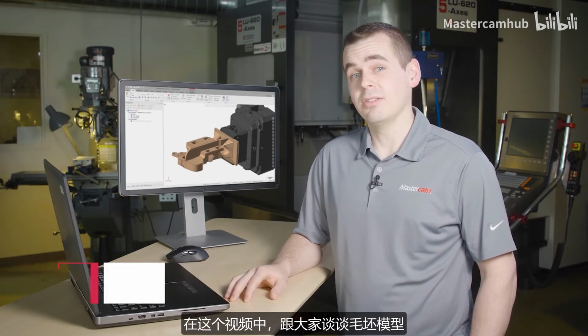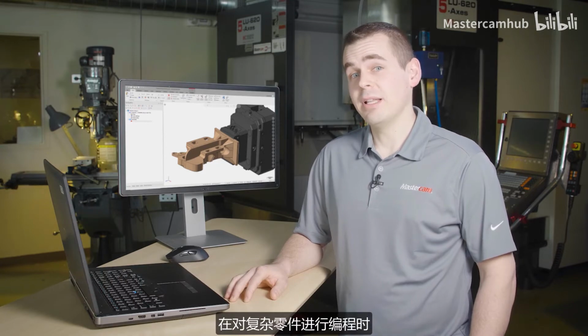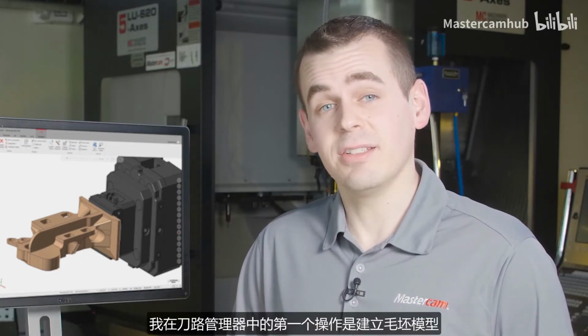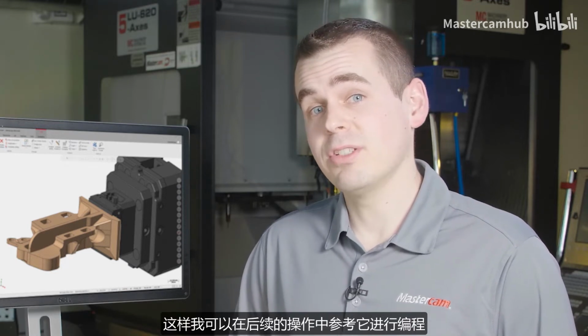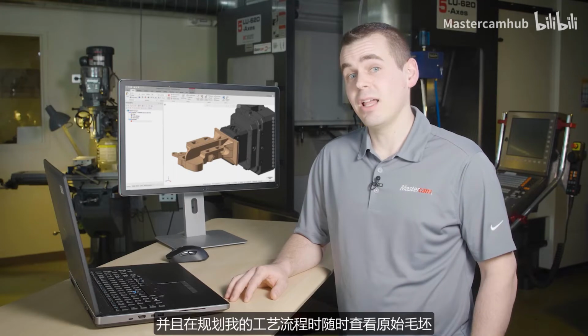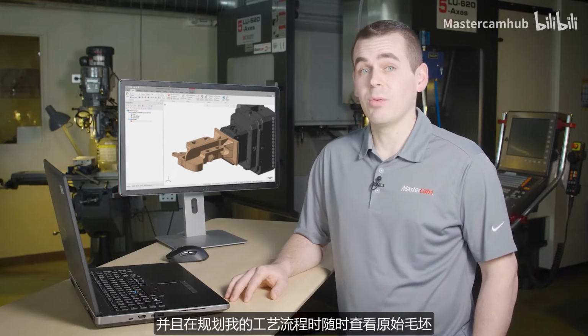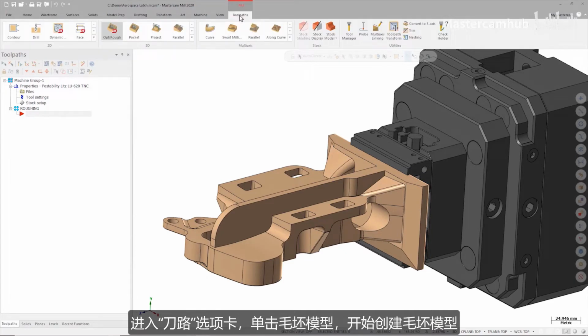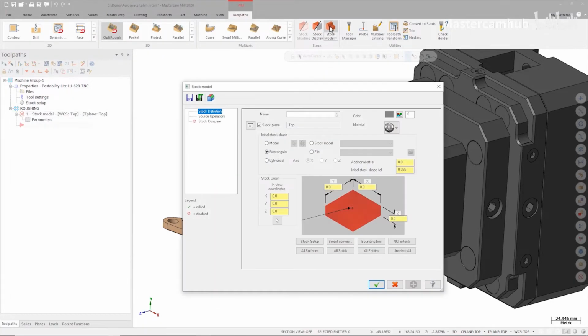Hi, I'm Jesse with Mastercam, and in this video I'd like to talk to you about stock models. When programming a complex part, I make sure the first operation in the toolpath manager is a stock model. I'm able to reference it for programming in future operations, and it makes it easy to visualize the raw stock when planning my workflow. To create a stock model, I go to the Toolpaths tab and click on Stock Model.